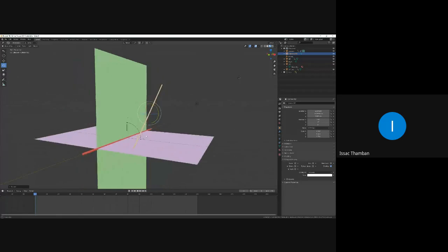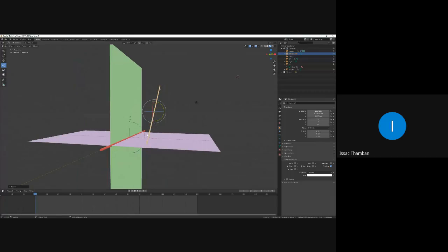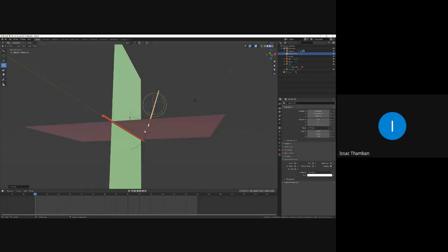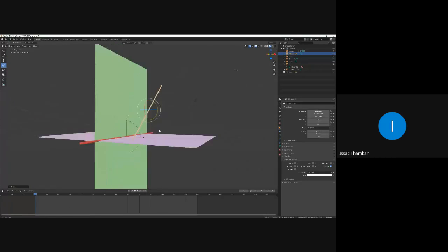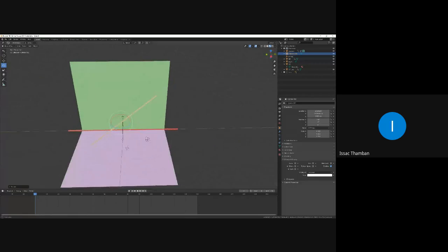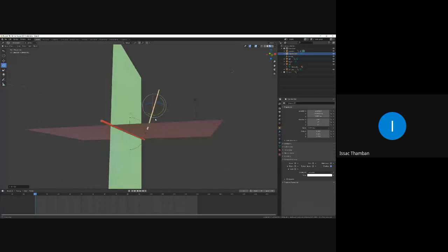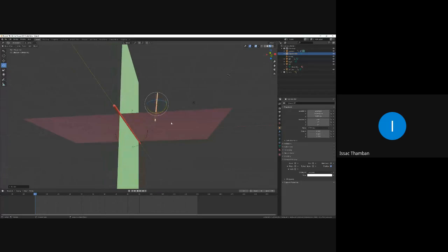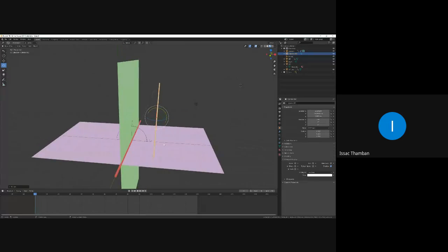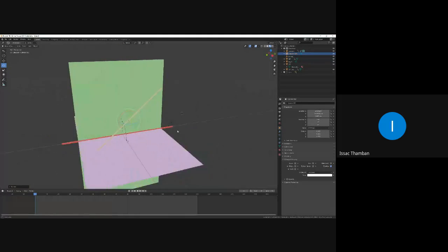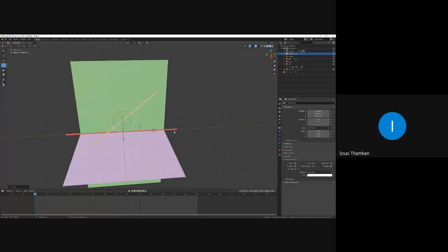In this particular case, the line has a finite length, but if you extend that line, it will penetrate through the horizontal plane at a point. That point of penetration is our horizontal trace.